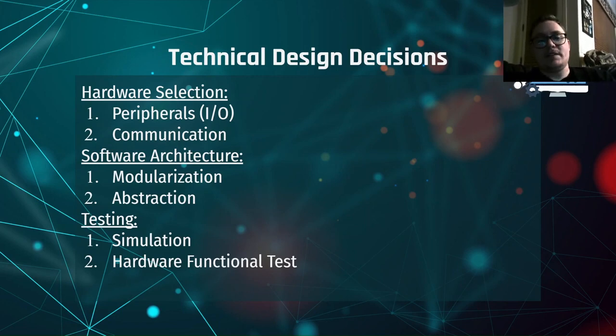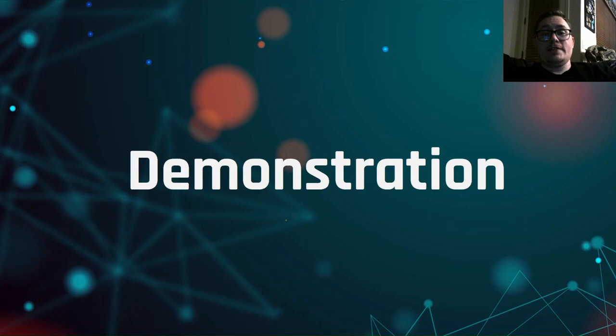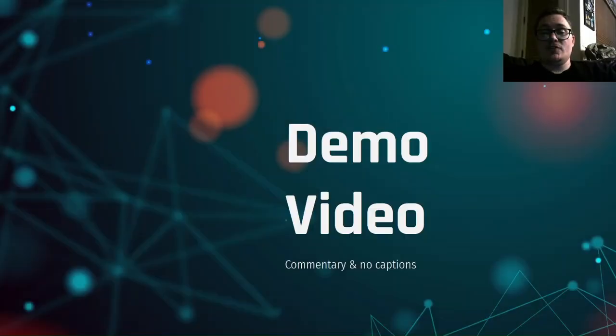But another aspect of that is testing. To get to my final third point, there was so much testing involved to verify each circuit, to verify each component of code, and not only was it done in, say, waveforms and simulations, but I also would make basic circuits and port that over to the FPGA and test them individually, piece by piece, so that it would all work seamlessly together. Alright, so I will go through a brief demonstration of the code.